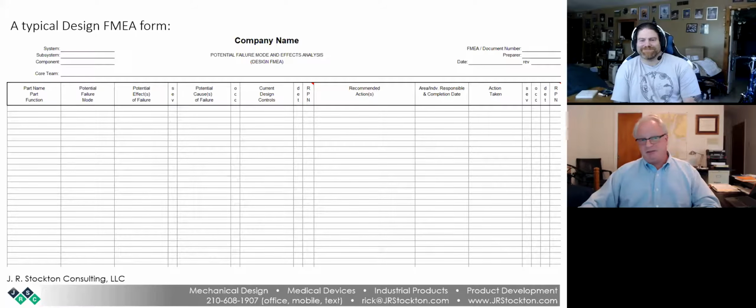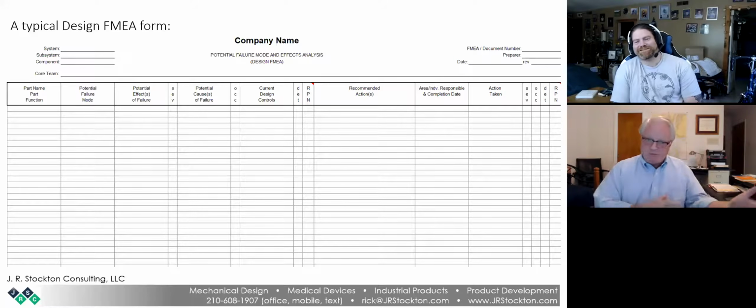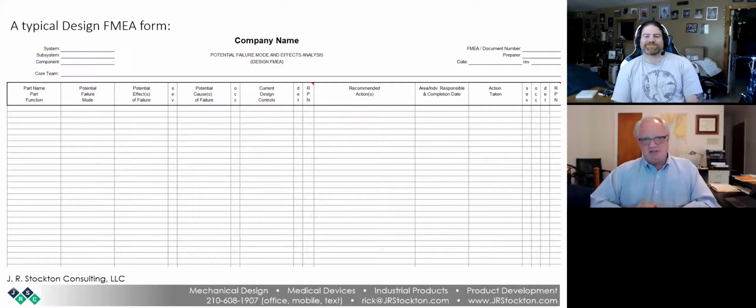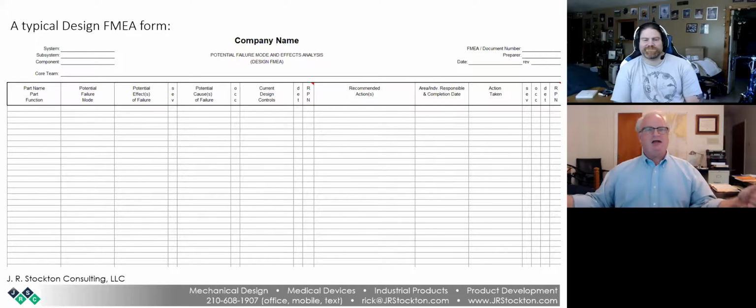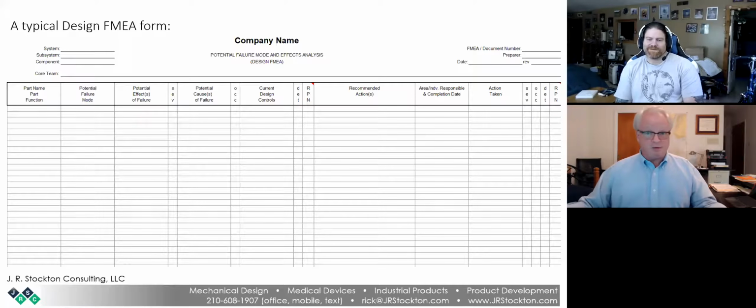So the best way to do that is to get all the information down, go home, set up a logical matrix that makes sense, that's consistent with your operating rules of your FMEA and everything like that. Bring that back to them, present it, and then challenge them to prove it's wrong. If you've ever been in automotive, you've had somebody from General Motors call you to dispute your FMEA numbers, and by the time the call was done, they were agreeing with your numbers, then you're ready.